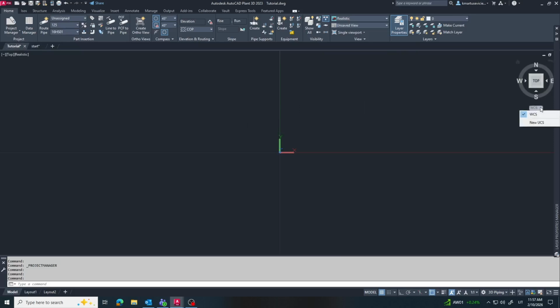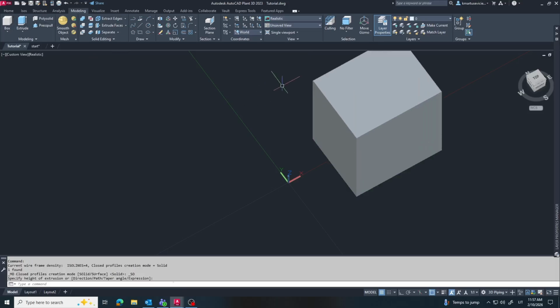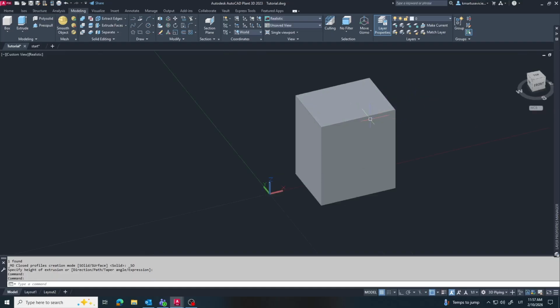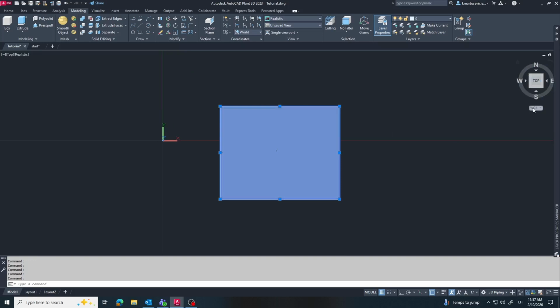Today we're going to talk about something fundamental in AutoCAD and Plant 3D coordinate systems. I'll explain the difference between WCS and UCS, how they behave after object rotation, and how to correctly align your working directions using the Coordinates tab. We'll build a simple cube, rotate it, and then create a new UCS aligned to the object, so you clearly see how modeling logic changes depending on your coordinate system. If you truly understand this, your 3D modeling becomes much more controlled and predictable.